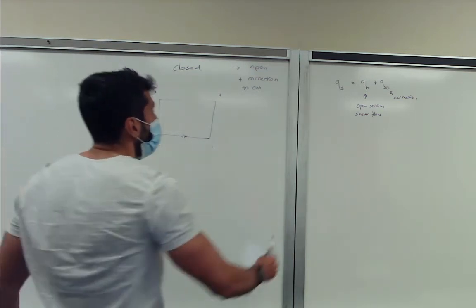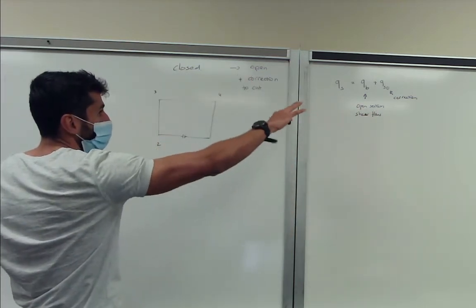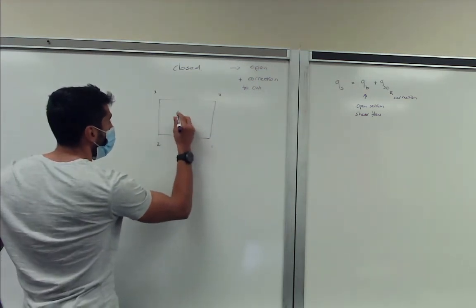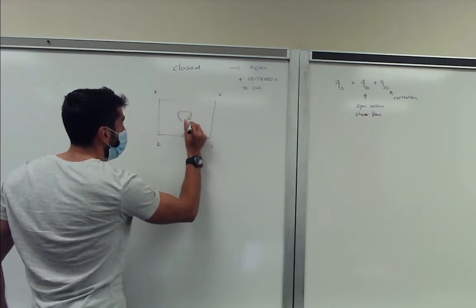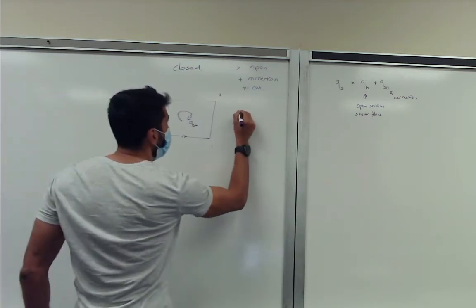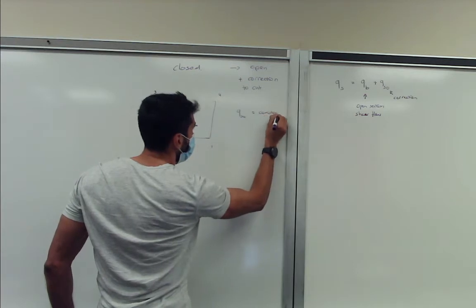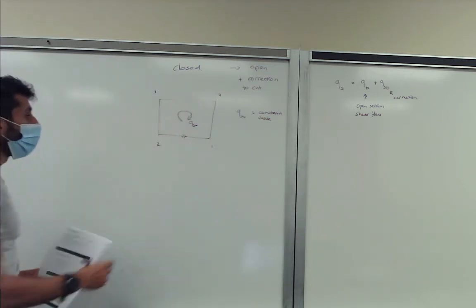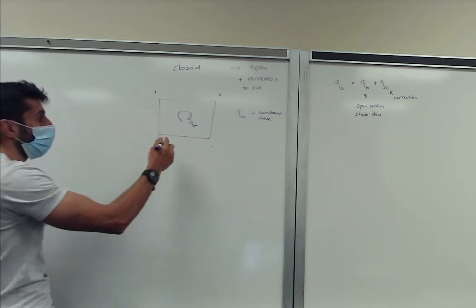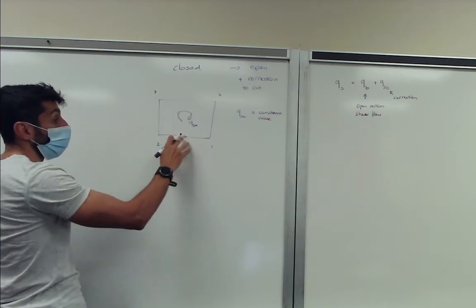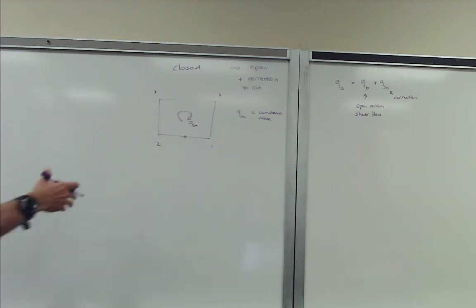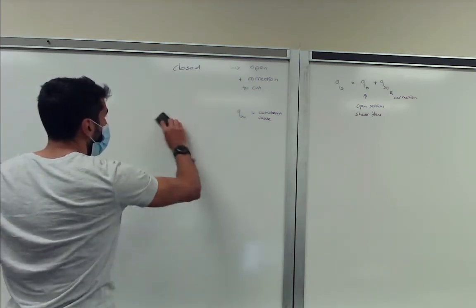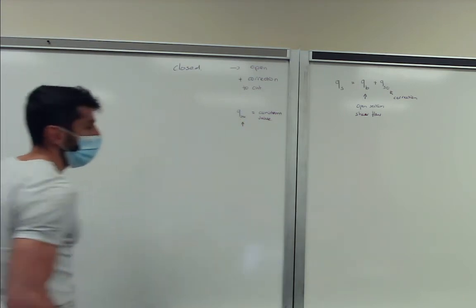In this, we have the open section, the q_b, and then we have the correction. The correction shear flow that we apply is basically a constant shear flow. So we also know that the correction shear flow, q_s0, is a constant value, because we can make the cut anywhere. Normally it will be closed, so you have a continuous shear flow. We have now made it open, and to basically close it out, we have to add a constant shear flow to that, and that will be added to all the points in the structure, of course, not just a single point. So we know that this is a constant value. With that in mind, we can start our derivations to see what this value is and how it relates to our cross section.